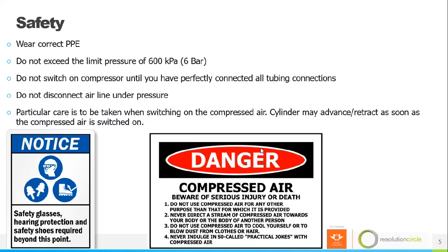You should not switch on the compressor until you have perfectly connected all your tubes. Because if you apply pressure in your system and some of the tubes are not rightfully connected, that may cause harm to you or to the people next to you.